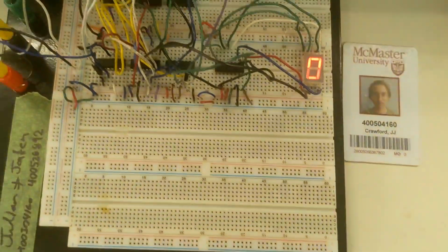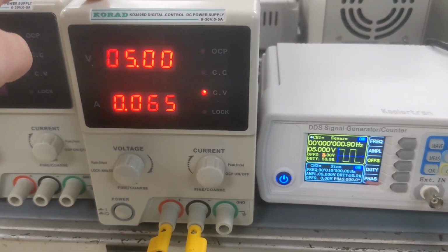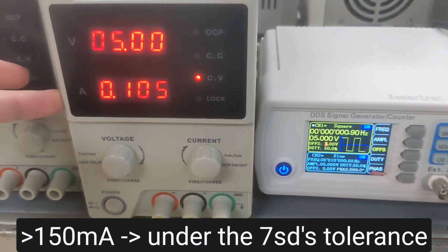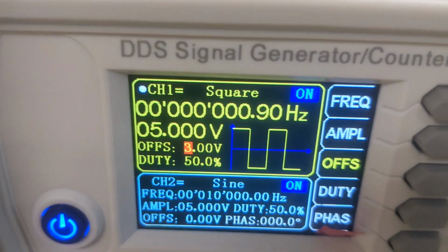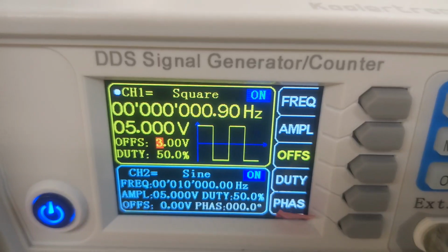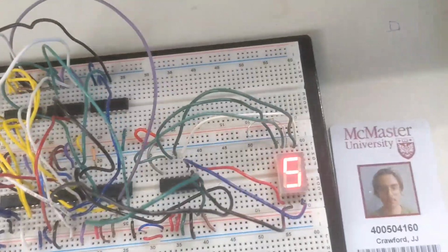Yep, so all in all, this functions. And we'll show that we're using a 5-volt input with a current of under 150 milliamps, with 0.9 hertz used as our clock to make it reasonably paced. We don't want it moving too fast.